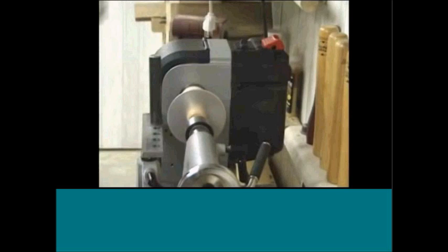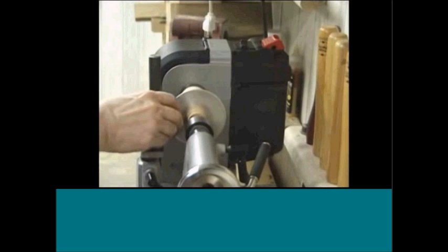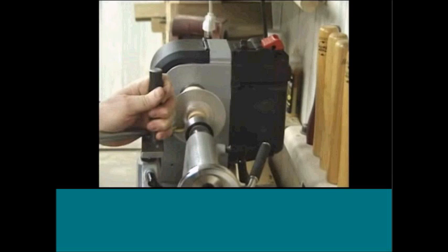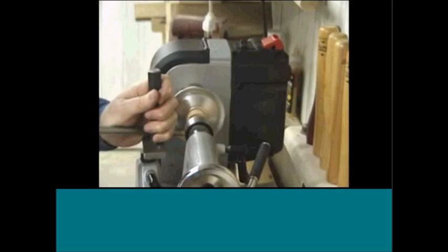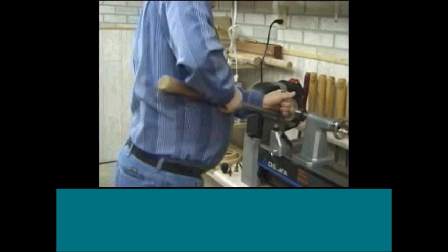Applying the lubricant. And now to start forming the aluminum disc over the mandrel. Notice the fluid is working from center to the edge while applying both downward and side pressure. The reason these tools are so long is so my body weight applies the pressure.